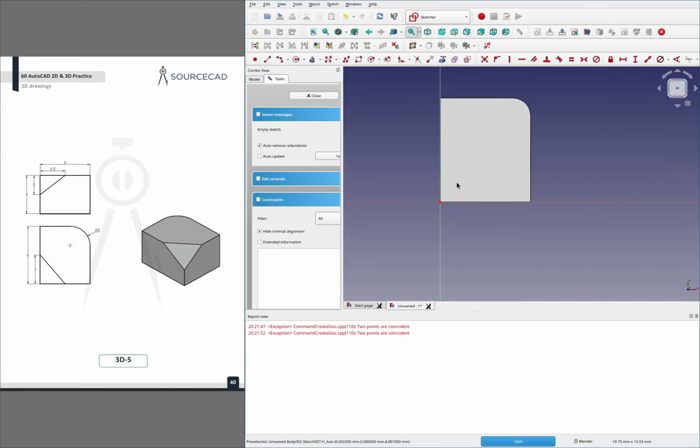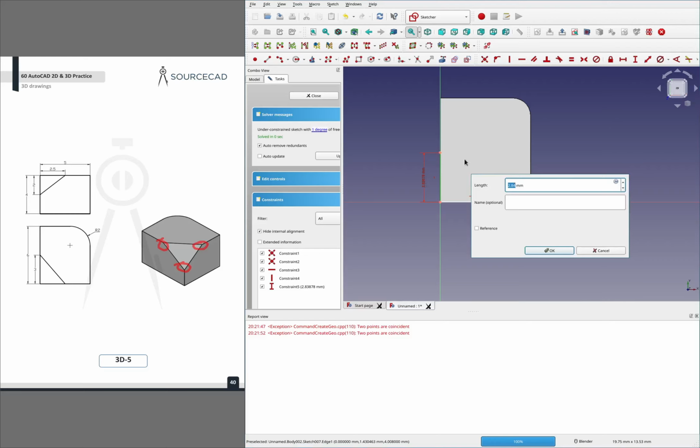So make a sketch here, and I will grab a line. What I'm going to do is sketch out this point, and this point, and I will use that to make a plane, and then I will use the plane to actually remove this section. So seems relatively straightforward. Hope it is as easy as it seems. Let's see. Vertical